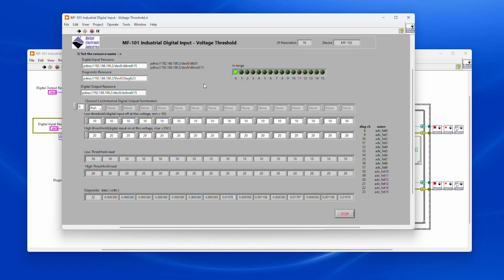With the pull-up resistor enabled, the line defaults to a high state. And when we press the button, which connects the line to ground, the input state changes to low, confirming the pull-up resistor is functioning correctly.